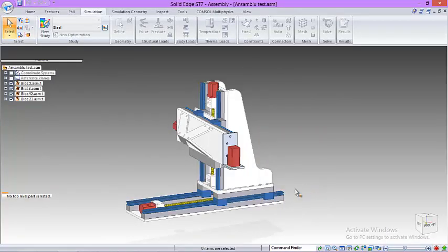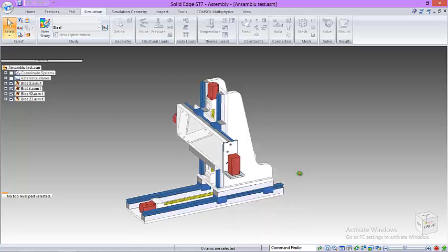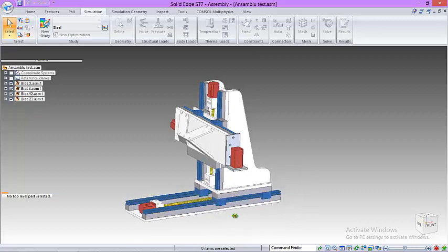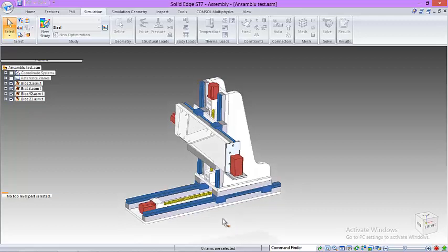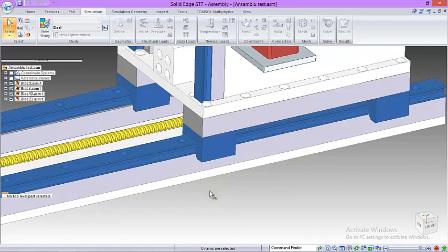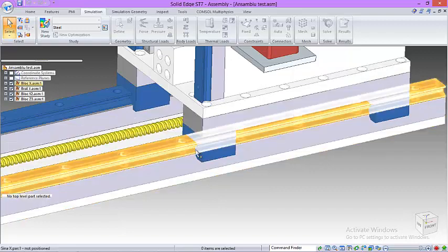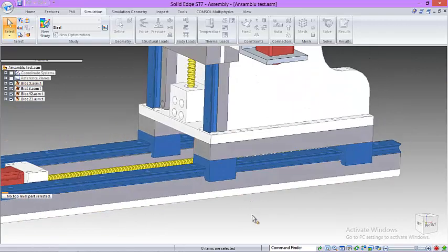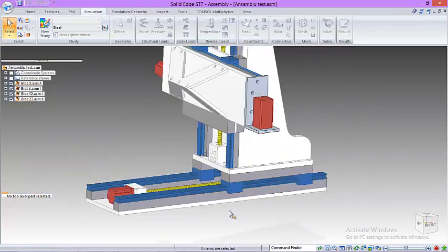Now we know that these linear bearings are going to transfer 35,000 newtons per cage, and we're going to simulate on this block that's going to be fixed to a concrete plate the surface of this cage on the rail on the z direction with 35,000 newtons.